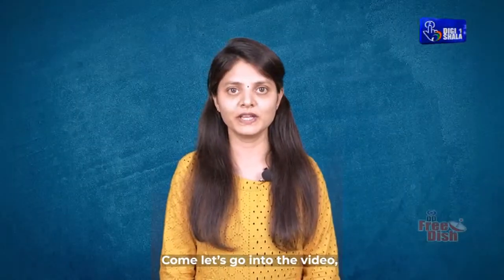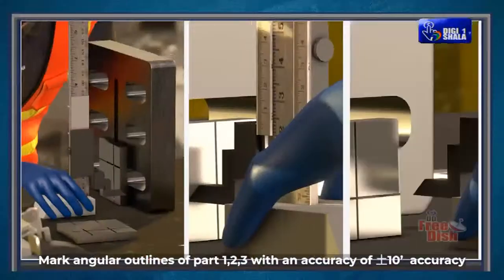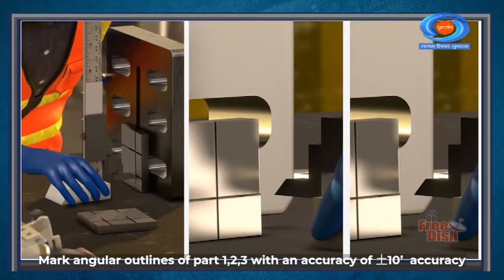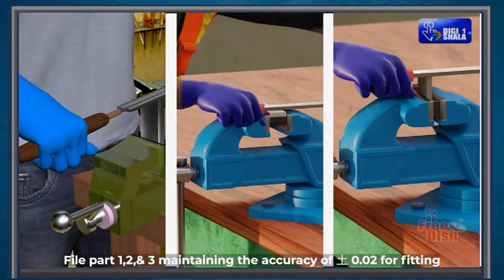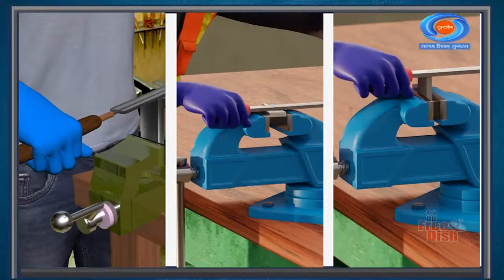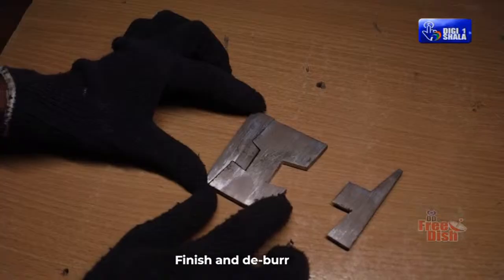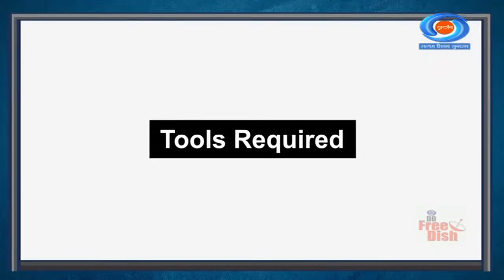Come, let's go into the video. At the end of this demonstration, you will be able to mark angular outlines of part 1, 2, 3 with an accuracy of plus or minus 10 minutes. File part 1, 2 and 3 maintaining the accuracy of plus or minus 0.02 for fitting. Assemble the part 1, 2 and 3. Finish and deburr.